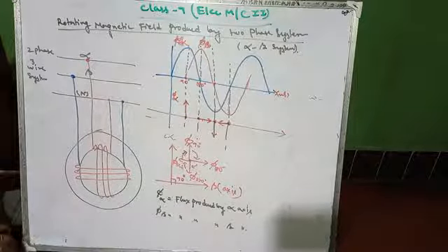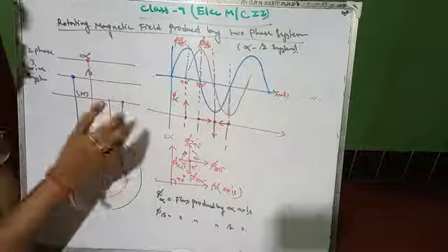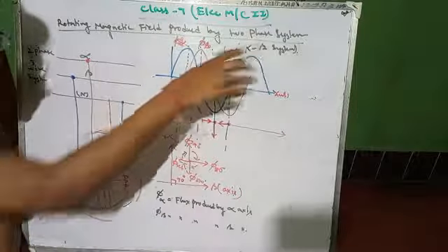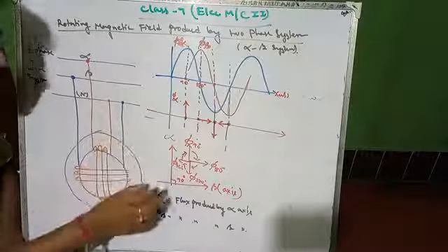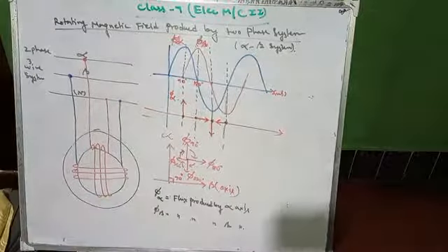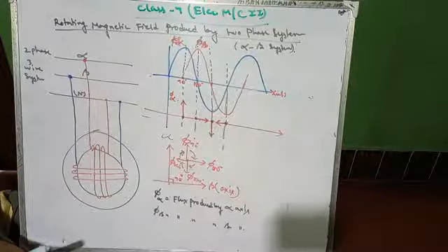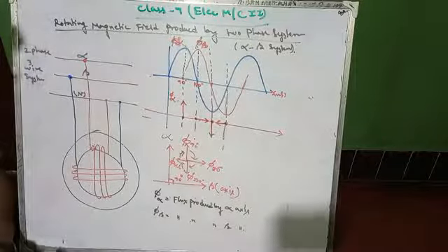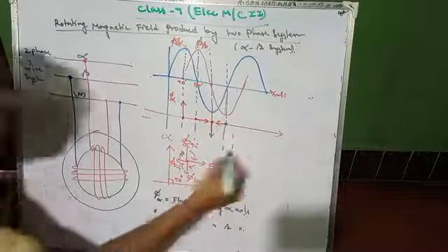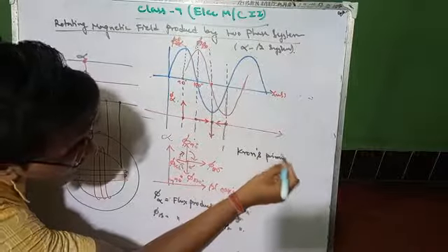So two-phase system can also produce a flux which is rotating in nature. This system is called alpha beta system, and it is very much important where it is applicable. This concept is applicable on your single phase induction motor system, in case of your single phase induction motor or Kron's primitive machine. Kron's, K-R-O-N apostrophe, Kron's primitive machine.